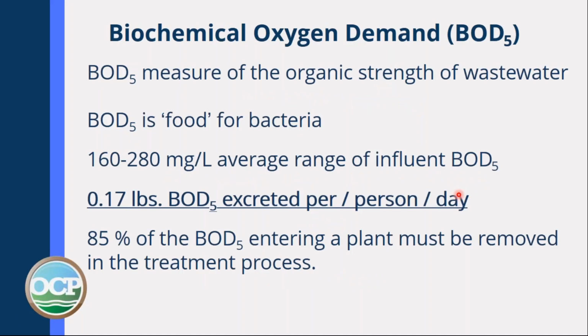So let's go back and look at some of those parameters that we have to test for in the water, both coming in and leaving the plant. So biochemical oxygen demand, BOD5. This really is a way of measuring how much organic material is in the wastewater.